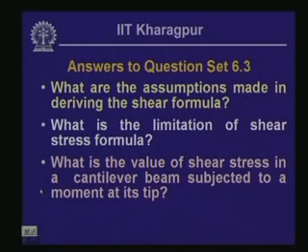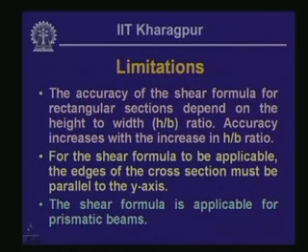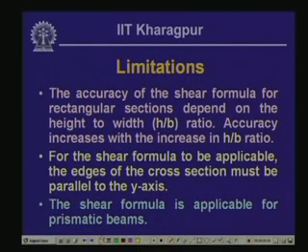Now, what is the limitation of the shear stress formula? You have seen that while calculating the stresses in a beam due to the shear force, we have used the shear formula VQ over Ib, and consequently we calculate the shearing stress at any point along the depth. Is this formula applicable for all kinds of beams, or are there certain limitations? That is what let us look into. What we had assumed, as you have just seen, is that the distribution of the shear stress across the width is uniform.